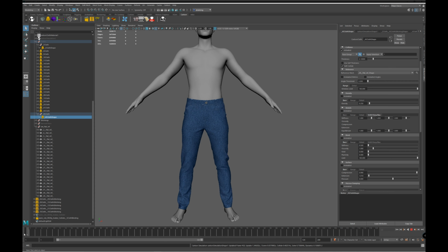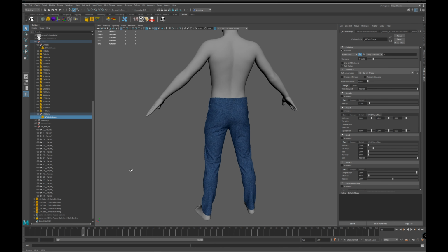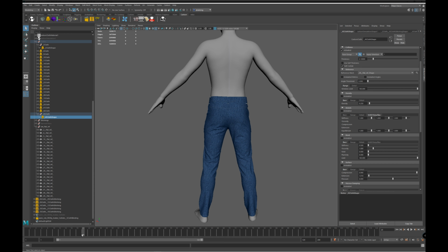You can swap back again to the start mesh as a reference following the same process, just selecting the sim mesh group as your reference meshes. The final point to reiterate is that you must be using flat panels in XY and the tailored model in order to have access to warp, weft and bias.